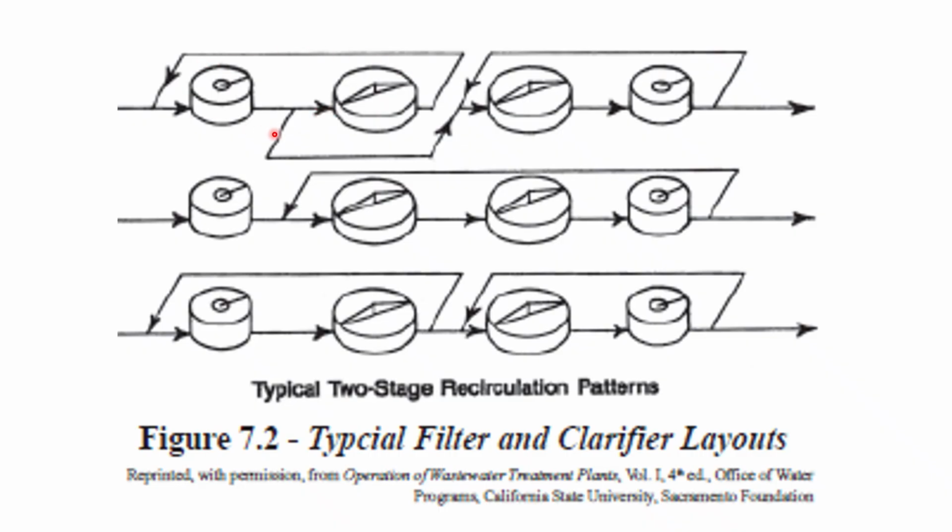Okay, so we've got this loop going on, and that's going to allow for a more efficient removal here by recirculating it here. And if there's any suspended solids here, they get another second pass at being settled out in the primary clarifier, and then we can split the flow.